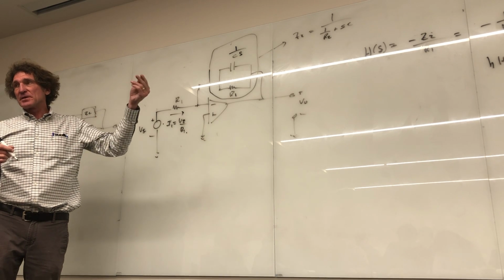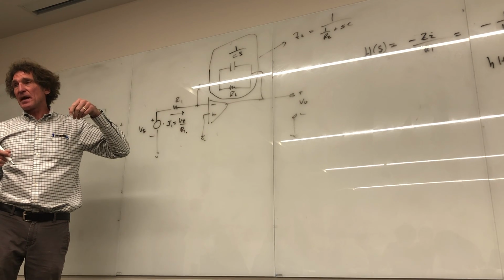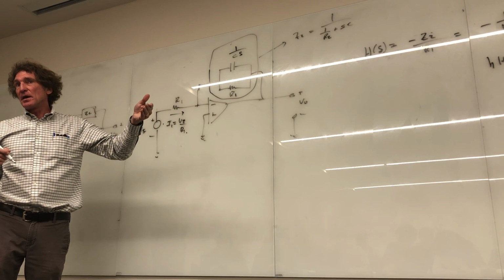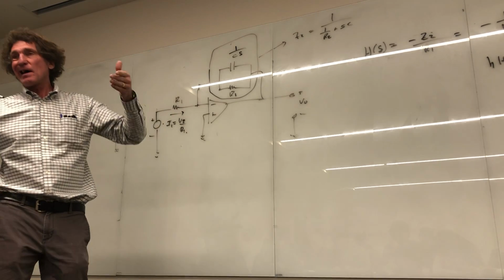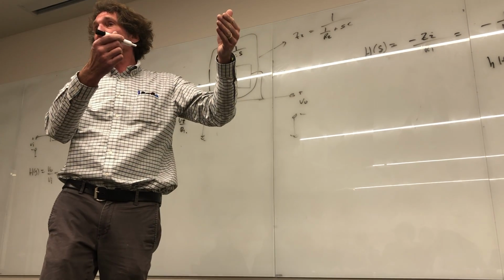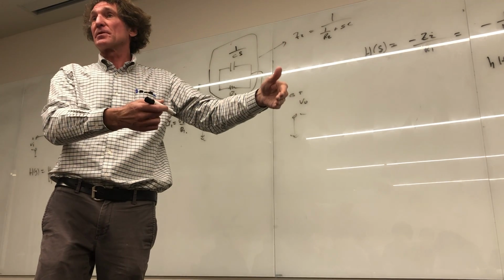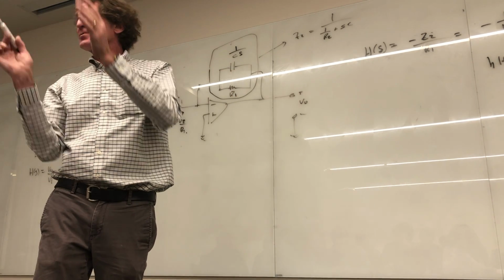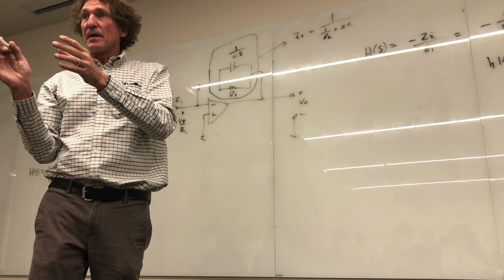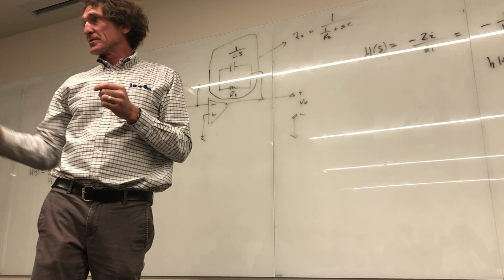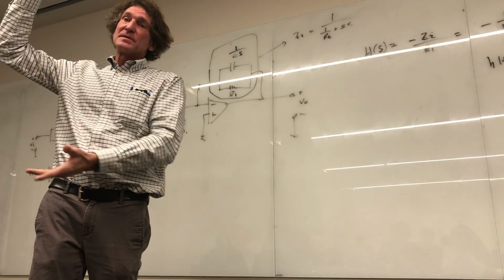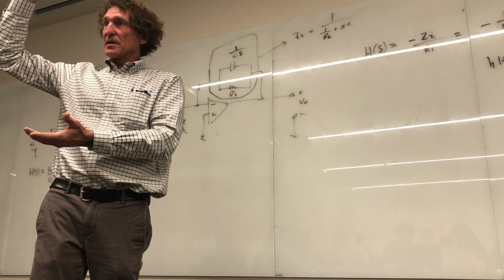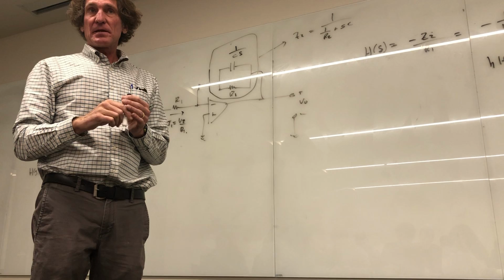Now, if I'm asking you to synthesize something, before I did that, I would probably give you some more drill problems on that, because synthesis, if you're going to actually build it with components, requires a lot more components in the circuit, right? Every time you have that 1 over S thing, you have an op amp. Every time you have a multiplier R, you have an op amp, right? And then you have to have a summer, which is another op amp. So you can get a fairly busy drawing. That might be more of a homework project than it would be on a test. That would take too long, unless it was a final exam. Got it on that, class?